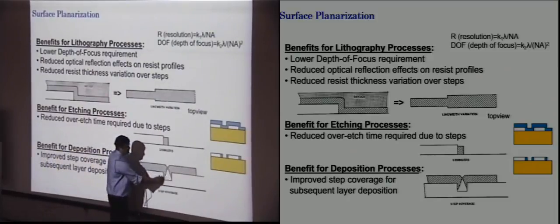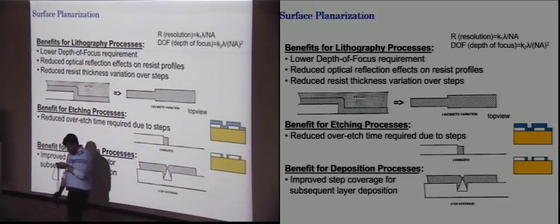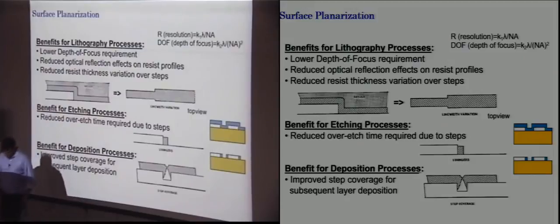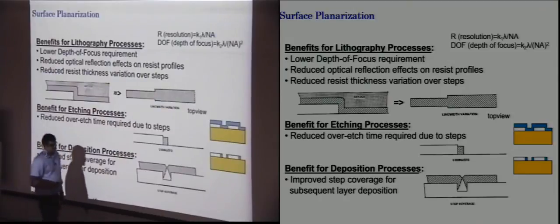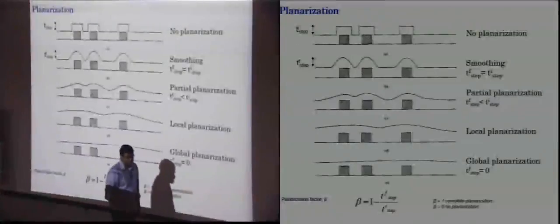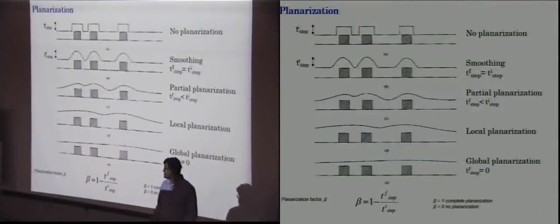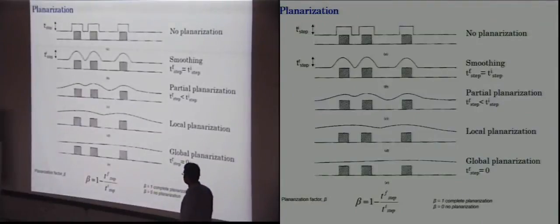So it becomes challenging to fill in the voids between these things, and therefore you could have problems associated with gaps, you could have problems associated with moisture or water stuck in the middle and then causing degradation effects later. Therefore, it is important to make sure we have more or less good step coverage and planarity to ensure fewer defects in the system.